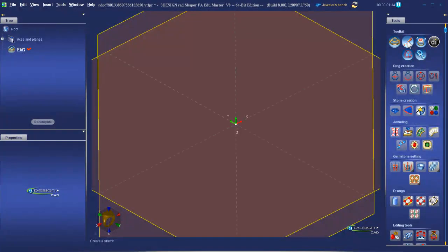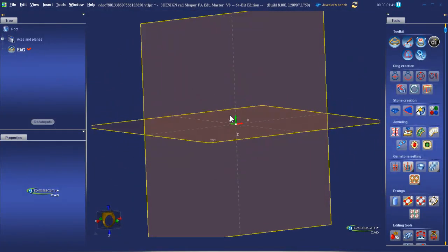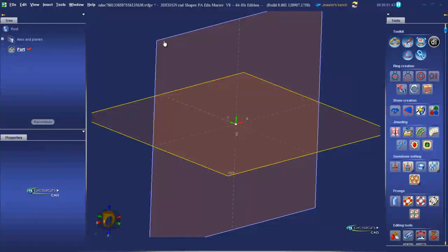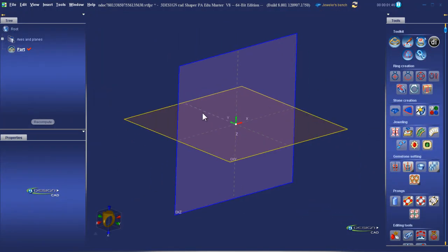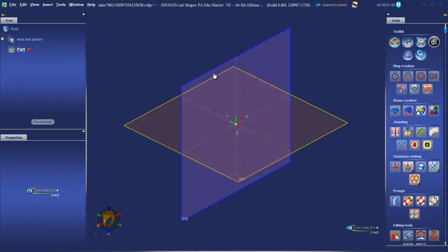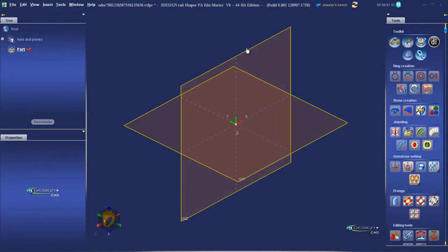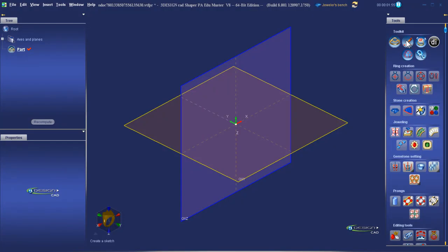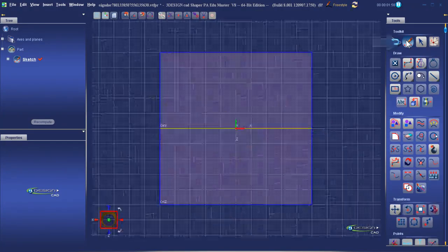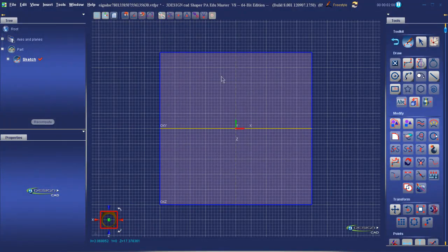Now, to start with, actually I could have accessed this from anywhere, but in the toolkit, I'm finding the sketch mode. I want to make sure I'm actually sketching in the right grid, though. I want to work on the OXZ grid plane here. So I'll make sure that's selected. You do it by selecting the edge. It'll turn blue, and go to Sketch. This will open up a sketch window, where we can start doing lines of any sort we want to on here. We only really need one line to start with, however, the basic ring.